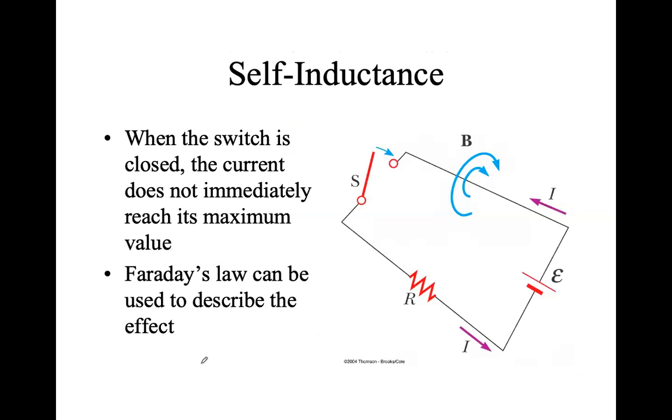And so I just wanted you to think about this simple DC circuit with a switch. And initially the switch is open, so there is no current flowing. And so there's no magnetic field anywhere. And I'm showing with some little arcs here, this leg of the circuit, the current's going kind of up into the left. And so we have a rule that says that means the magnetic field swirls around that piece of the wire, and it does the same thing over here, and over here the current's going that way. So I guess it goes under the bottom over the top here.